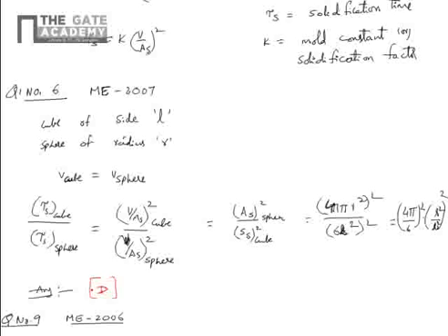The time taken to fill the mold with top gating is TA, and if the same mold is filled with the bottom gate, then the time taken is TB. Ignore the time required to fill the runner and frictional effects. Assume atmospheric pressure on the top of the molten metal surface. Find the relation between TA and TB.